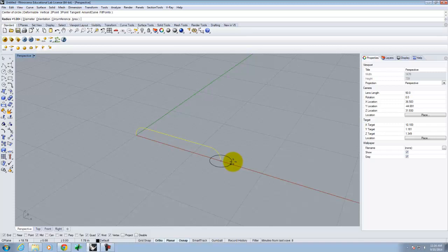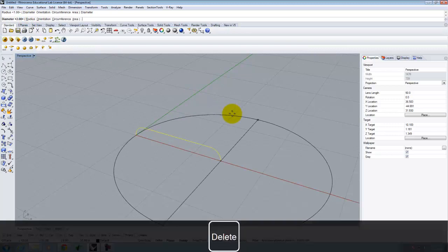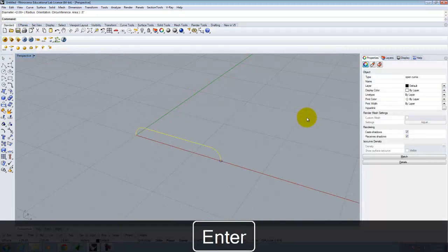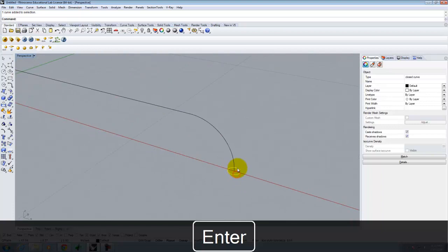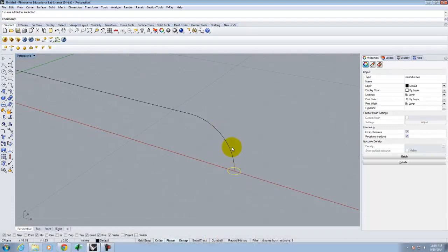And I want that to be the diameter, not the radius. So I'm going to click on diameter here, and I'm going to specify that as 0.5 inches, okay, which creates that little circle at the end of this object. Does that kind of make sense?